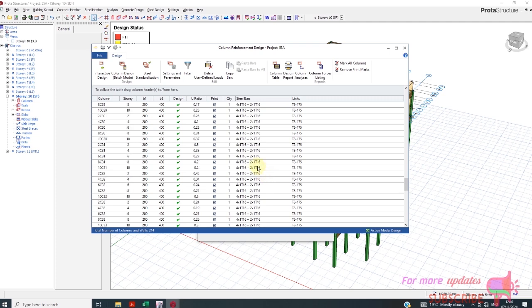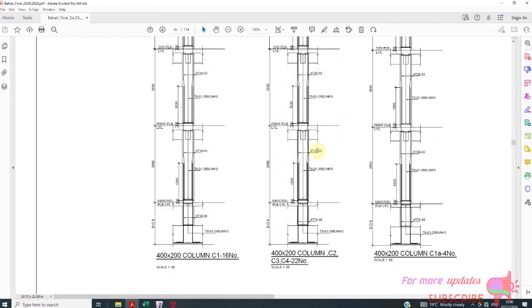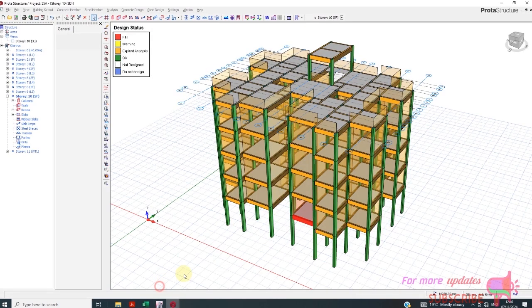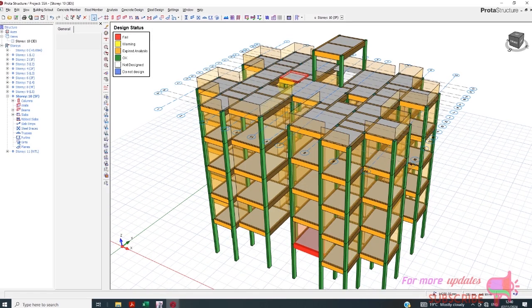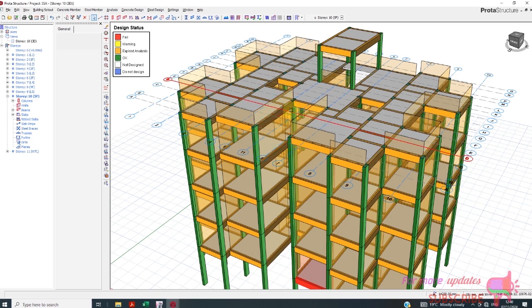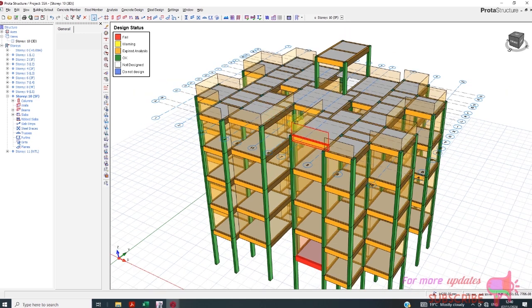So I'm going to go with the value for item. So I think every time you are designing, don't under design, don't underload your slab. The value should be not less than 2.5 extra dead load on slab.